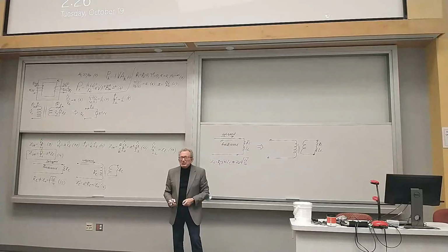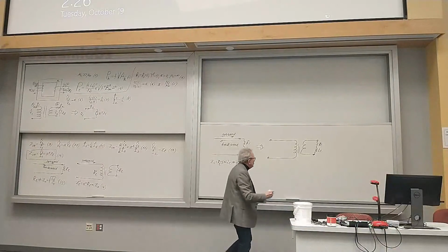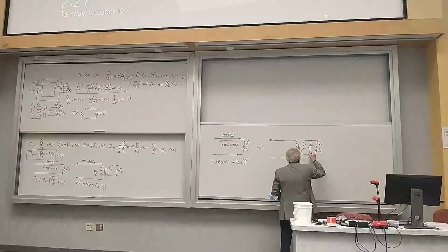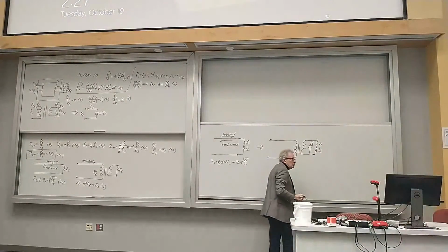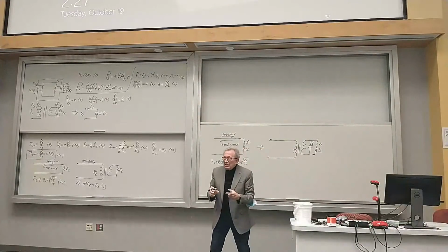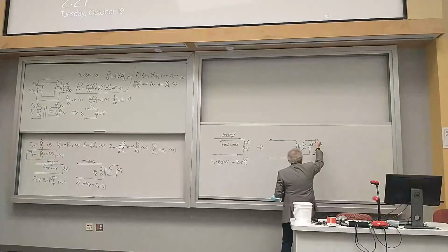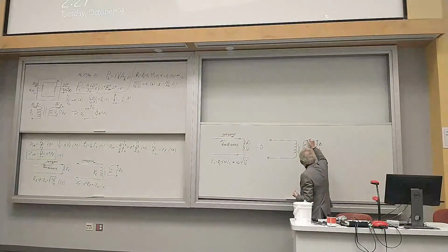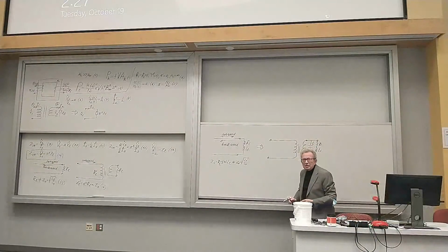This is a simple trick, we already studied it. We studied it when we discussed adjustment of power factor to 1. This is the trick where you put a capacitor across the load and choose this capacitor in such a way that all these connections across these terminals behave as a resistor.